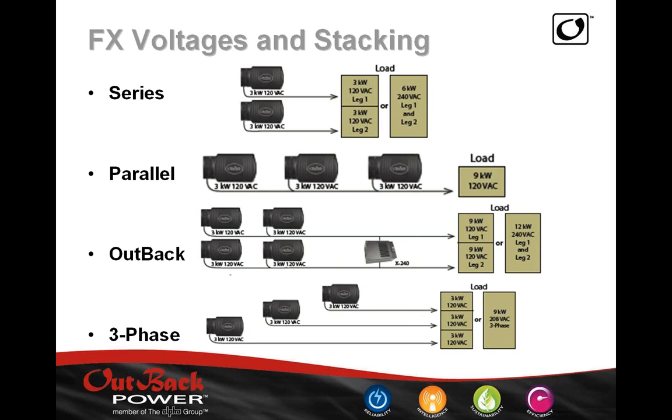Now, if you had a single-phase load that used 3-phase voltages, for example a load that only requires 2 phases, but at 208, with a phase angle difference of 120, you can program our inverters to do just that, to provide a 3-phase source with only 2 phases, either phase A and B, B and C, or phase A and C.